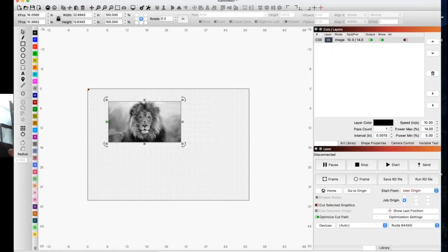All right, we have an image, and of course, I think I've told you, Grant and Brian, if you're bringing garbage in, you're going to get garbage out, and that is always the case. So we want the best resolution we can. Lightburn does get a little laggy when we get up to about 1,000 DPI, but it can still process it if you give it some time. You've got to remember that all of these processes that Lightburn uses, you're getting a dot pattern. You're getting a breakdown of the image in dots, and to create a better dot pattern and create a better image for the laser to use, you want to give Lightburn as much information as possible. So anywhere between 300 and 1,000 DPI should be excellent to achieve great quality.